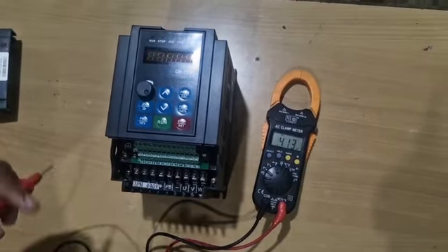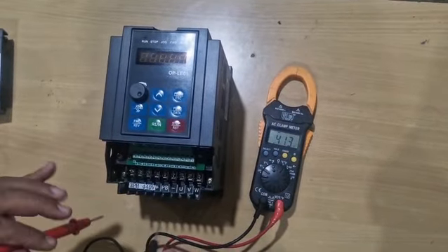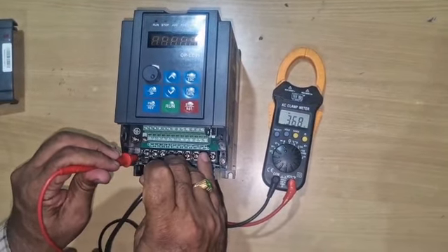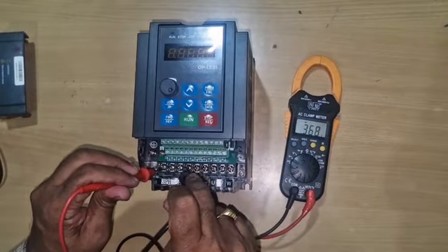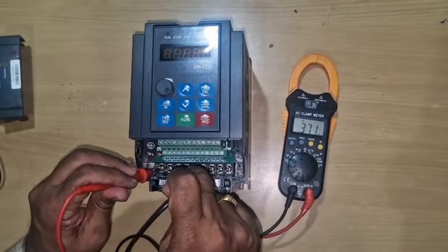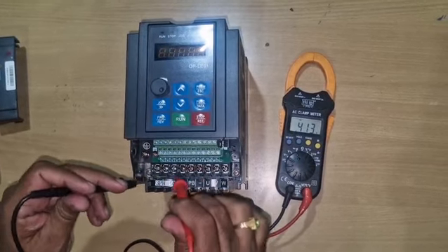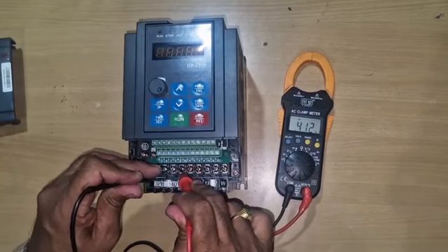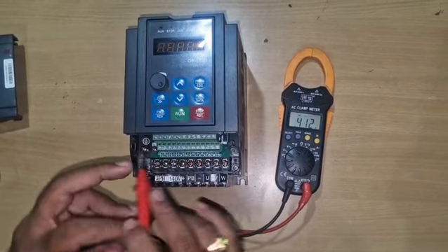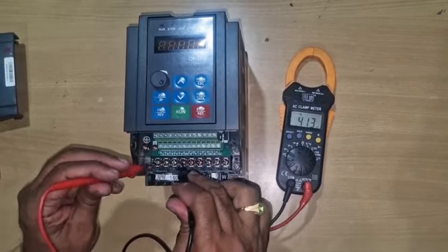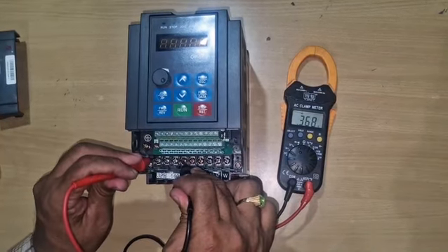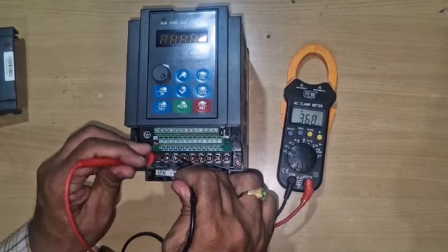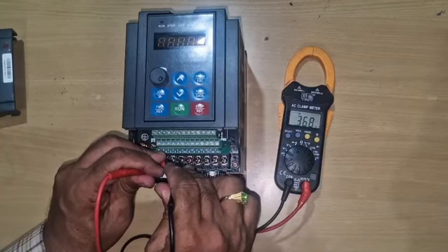How to test VFD? When you give input 3-phase, it is a forward bias. Forward bias means positive on the anode, negative on the cathode. If you keep positive on the anode and negative on the cathode the other way, it becomes reverse bias. It is showing 0.41 volt in diode mode. Next, if you change to forward bias, negative on the positive side, positive probe on the RYB, it is 0.36. It is the forward bias voltage of the semiconductor.